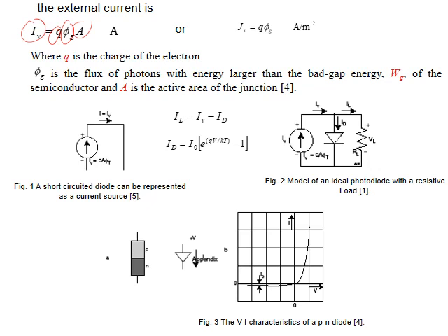Now this is the current, as I mentioned. This is the production of current from the photon energy that came. Now the operation principle of the cell itself: it's a p-n junction, so it's represented by a diode, as you can see here, right? So the current coming from here, part of it goes here and part of it goes to the external load. So I can write I load is IV minus the diode current. Very simple circuit, you studied this even in secondary school.